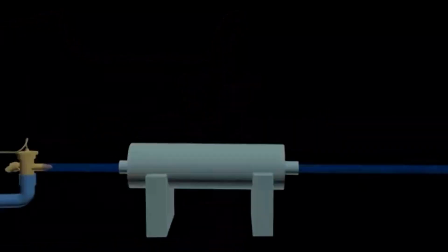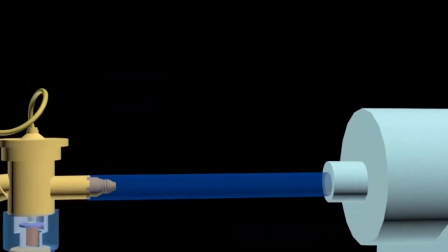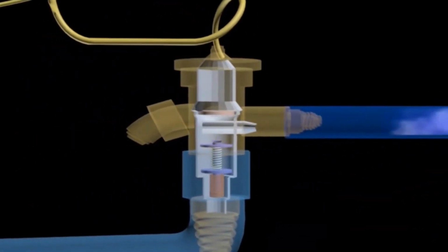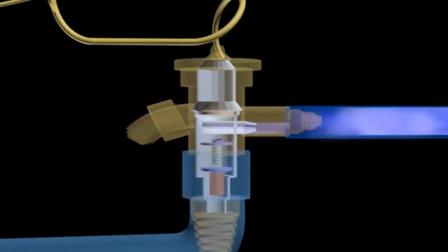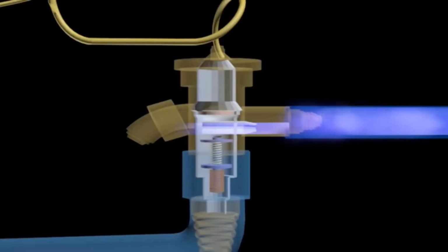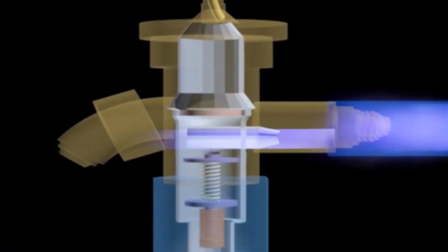Expansion valve. The expansion valve serves to reduce the pressure and control the flow of refrigerant going into the evaporator. When the pressure of refrigerant has declined drastically, the temperature will drop dramatically, which is lower than chilled water temperature. In a centralized system, the expansion device used is the thermal expansion valve (TXV) type.